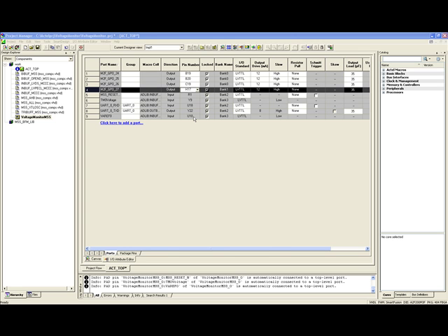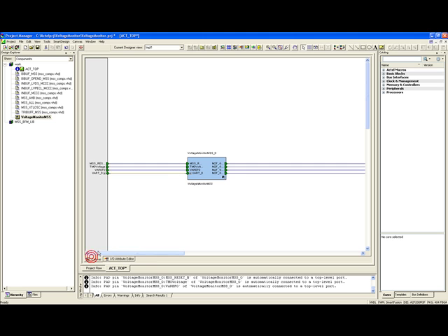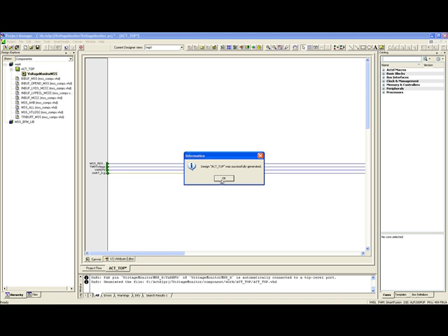Now, right-click on any of the unused parts of the SmartDesign canvas and select Generate Design. This action will design rule check and convert your project into a synthesizable HDL file.